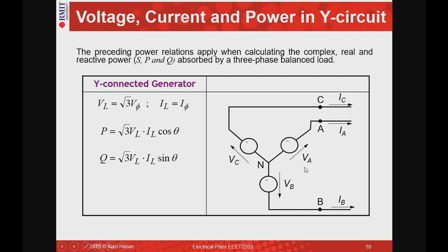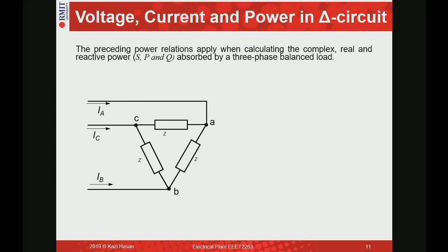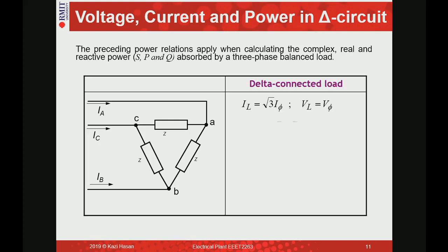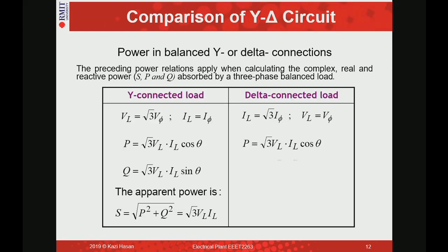Because this is very high voltage, it needs some grounding, so sometimes they ground it here. So in Y connected circuits, there can be a 3 wire system like this, or there can be one more connection, like a 4 wire system. But in delta, it is always a 3 wire system, because there is no common point in here. This is just some general information when we compare these 2 systems together.